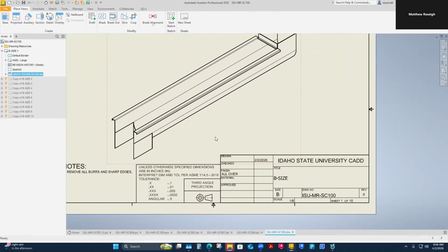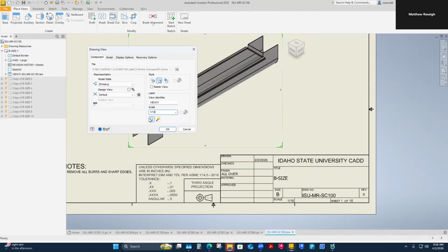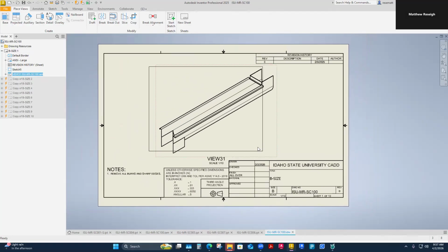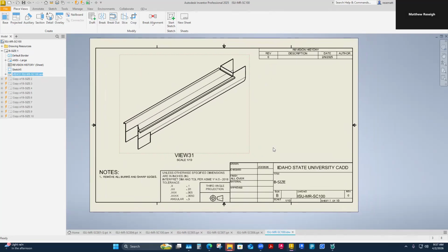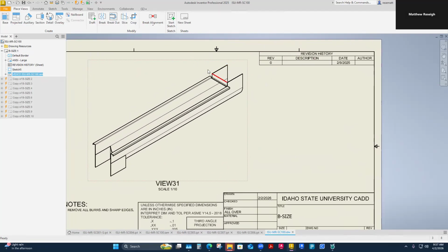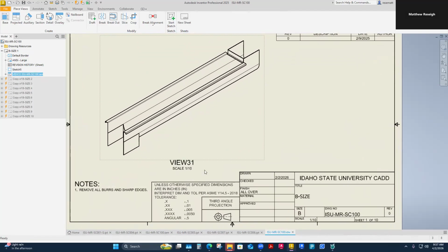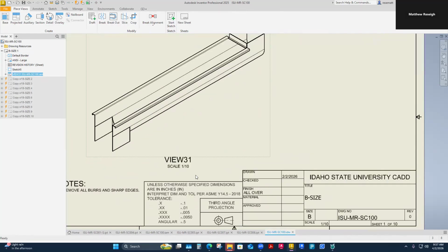And I still need to make it so it fits. It's going to grow out a little bit from here. So I'm just going to edit its scale, from an eighth of an inch. Oh, I don't know. What are we going to go? Like a tenth maybe? Tenth scale. And since I don't have the other orthographic views here, I'll add a view label to this isometric view, which we'll adjust in a bit. So it might come over here and be something like this. This might even get smaller as we build this out and we have a big hopper here and some of the discharge stuff, but this is at least a good start. So I'm planning on this view being my isometric with callouts.